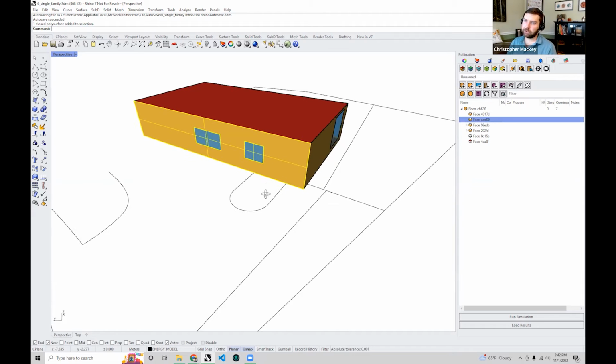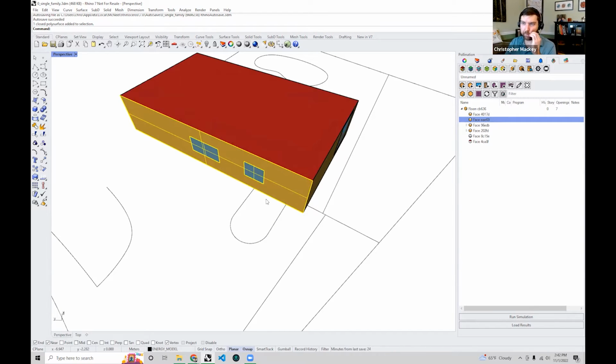Yeah. So I know by default we tend to try and pull the IDs from elements within the Revit model, which the good thing about that is, as you'll see at a later point, that it allows you to always match things back at later stages of design if you want to pull in things from that model. If you get to a point though where you're like, all right, just give me some clean readable names, there is a command that we have called reset identifier.